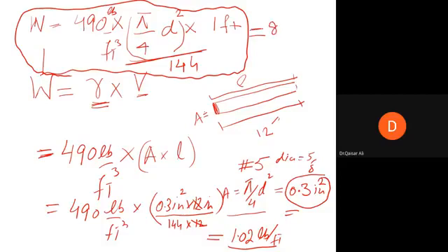2.67 is equal to 8 by 3, isn't it? Yes, sir. Okay, so it means that you can calculate the weight of 1 foot of steel by 8 by 3 d square. Now you can do this again. D equal to 5 by 8, or 5 by 8 whole square multiplied by 8 by 3, you will exactly get the same answer.